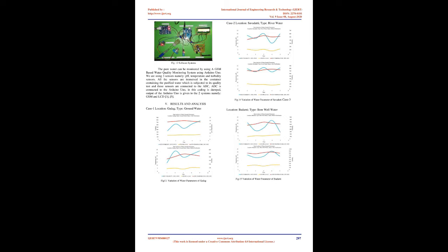Different components used in the hardware system are as follows. As shown in the below figure, the parabolic solar collector is made of stainless steel for obtaining maximum reflection of incident sunlight. It helps to kill the microorganisms present in the water with the help of solar radiation. It is set in the north-south direction and tilted at an angle of 45 degrees with respect to the sun.